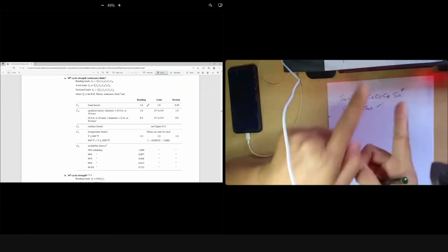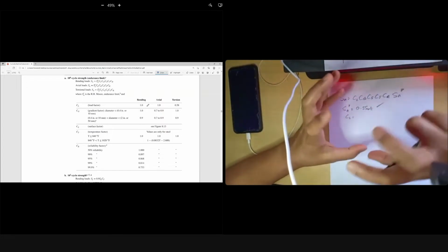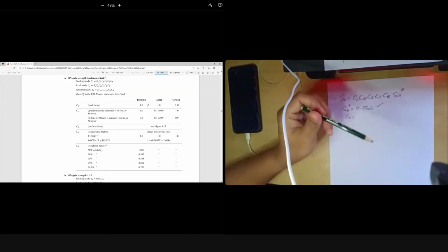Sometimes the torsion is big, for example, if your pulley radius is very big and produces a big torsion, the force acting on the belt of the pulley is very high, like a heavy-duty crushing machine, or the gear tangential force is very big, or the belt tension of the pulley is so big. It means the torsional stress is much bigger than the bending acting on the shaft. Sometimes it happens that the tau M, in megapascal, is even bigger than your sigma. It means torsional stress governs, so you cannot use bending, you go for the torsion value. Is it clear, class?